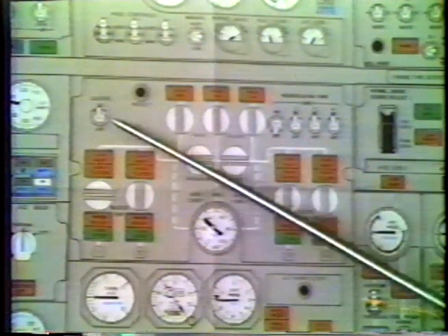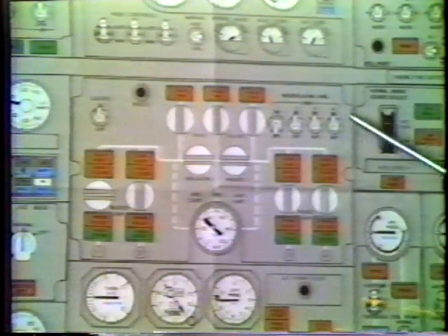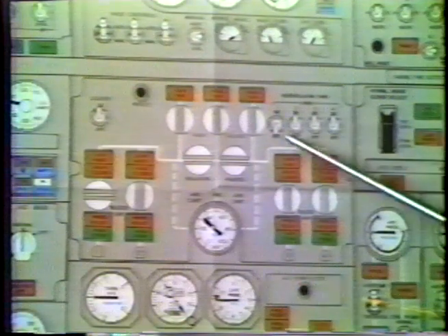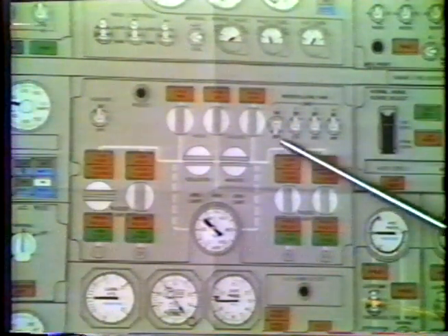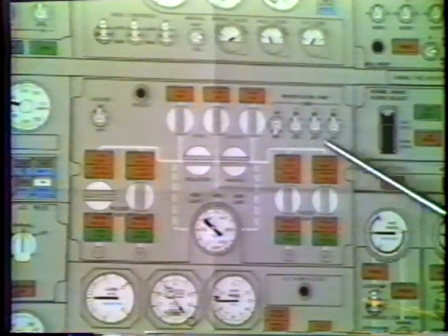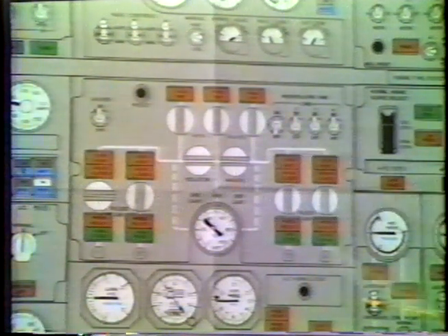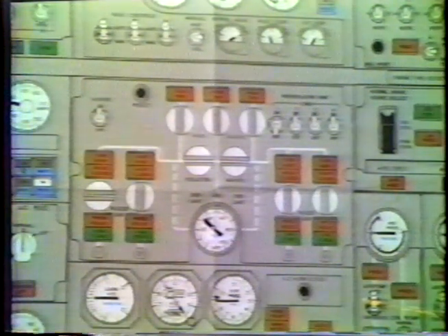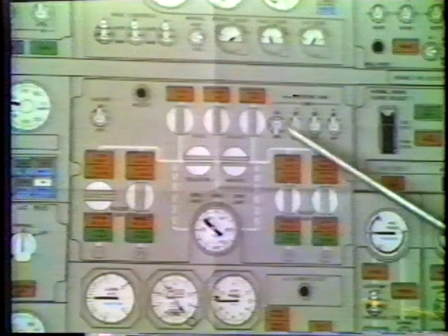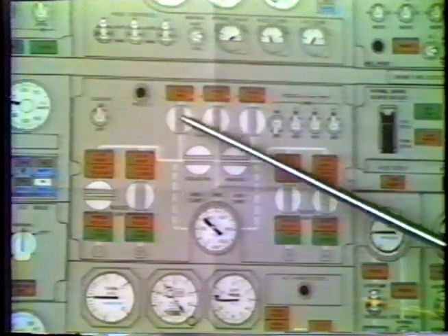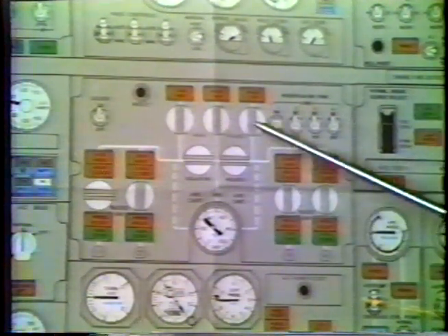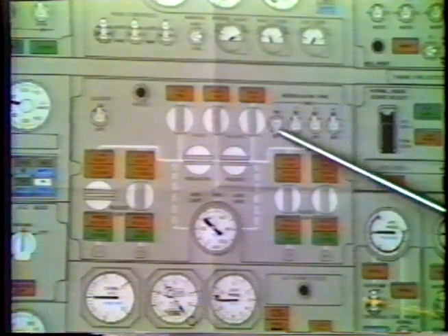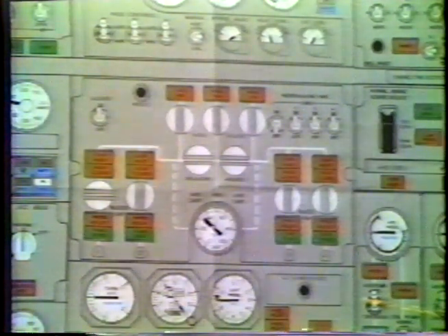Normally, the Gasper and Recirc fans are on all the time except the number 1, which supplies air to the cockpit. The switch, when it is on, supplies air of a volume, and it makes quite a bit of noise. Unless it's absolutely necessary, it normally isn't used. The only time it is used is when no air is available from the pneumatic system and PACs can't operate it. It does bring some air to the cockpit from outside.